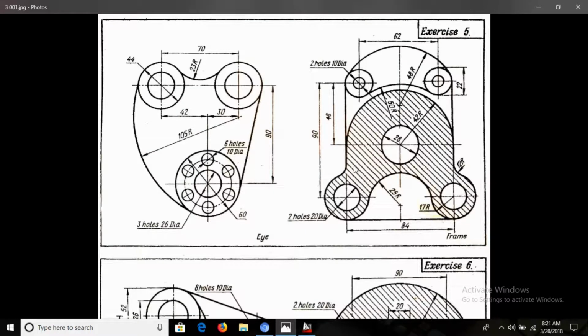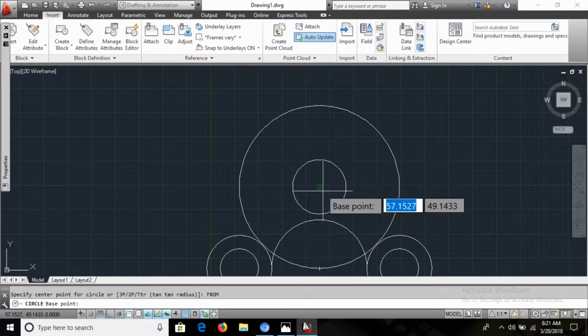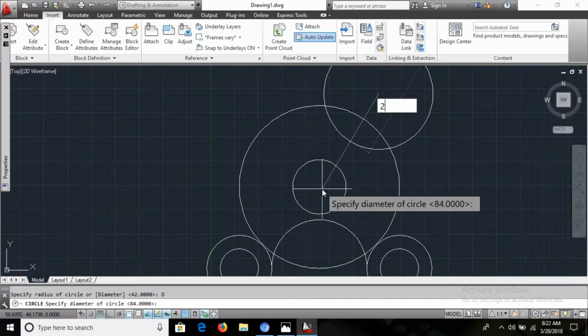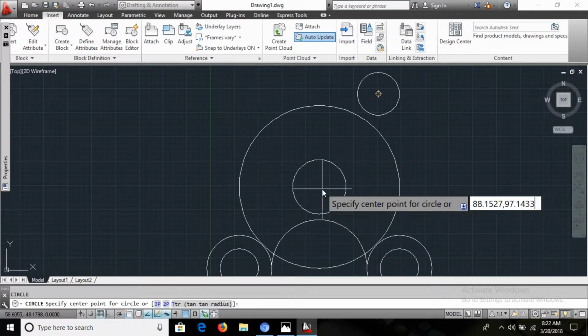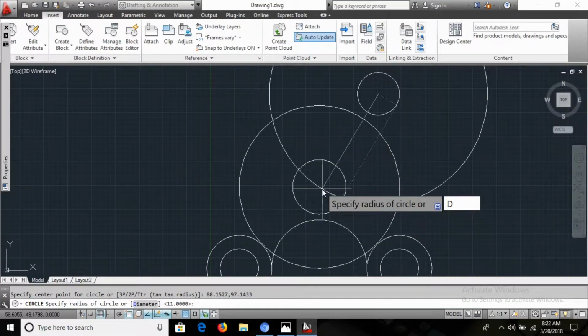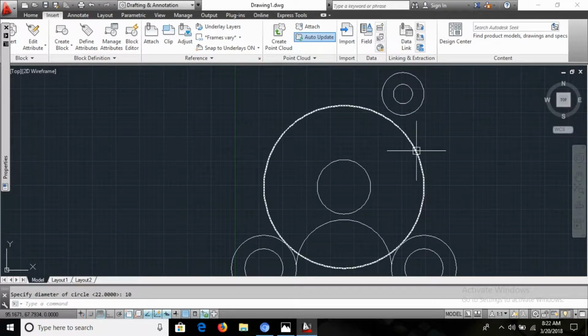And you can see now, I have another circle over here. But before going to that, I'll discuss this here. From this to this, I have 48 as the height and 31 as the x. So it's C enter, from enter, base point is here, and at the rate of x value is 31, comma, y value is 48. D enter, diameter is 22. Okay, C enter, circle there, and diameter is 10, I think so. D enter. Now we need to take a copy here. CP command.